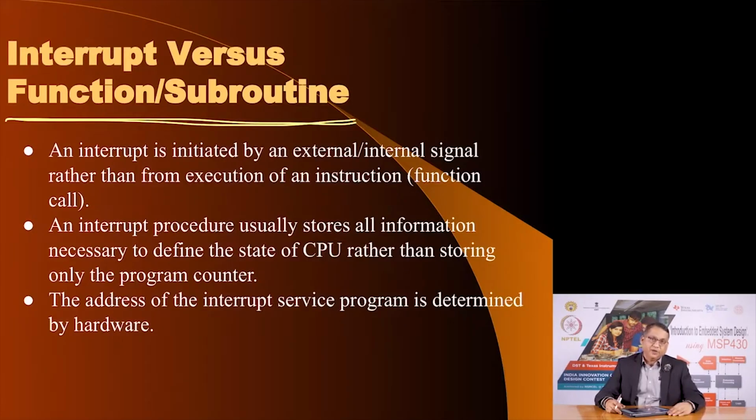In the case of an interrupt subroutine, you do not know when you get called, and therefore you need to store not only the address of the instruction which you were executing or would have executed onto the stack, but also the state of the microcontroller. The state of the microcontroller here refers to various flags like zero, carry and so on. So, even those need to be saved on the stack.